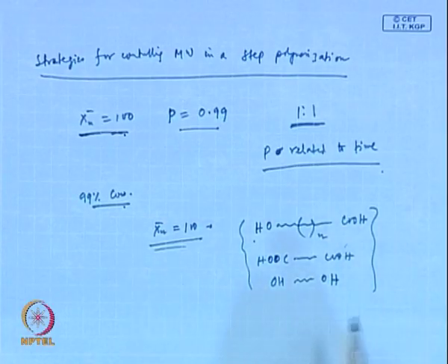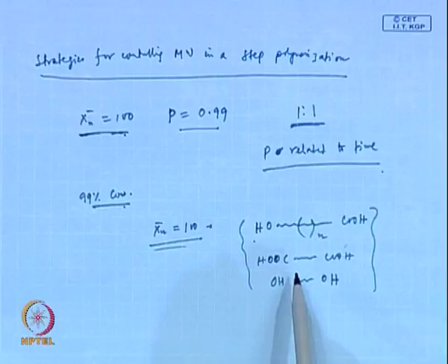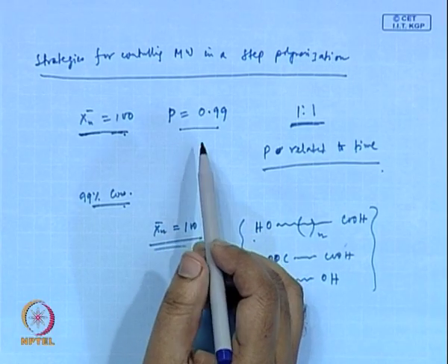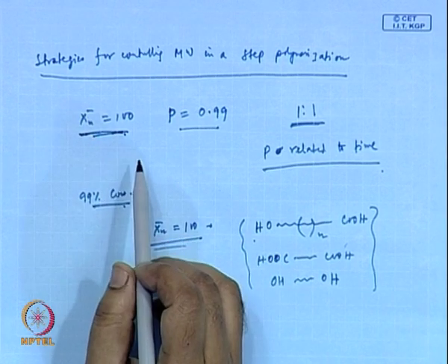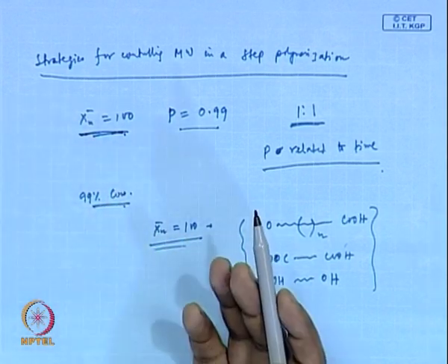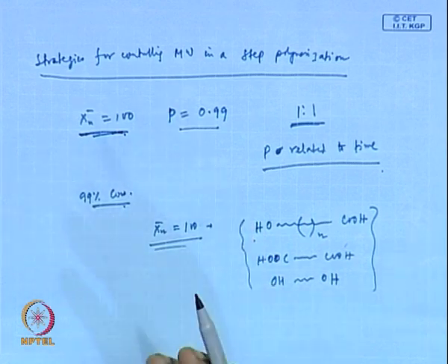So, these can react with each other or with the polymer backbone and degrade the polymer or build the molecular weight. So, at the end of your molding step, the molecular weight might be different than what you targeted for, so your properties will be different. So, it is not advisable to stop a reaction in between at the level you targeted. So, how can we achieve that? What are the strategies we can use to achieve what we targeted?